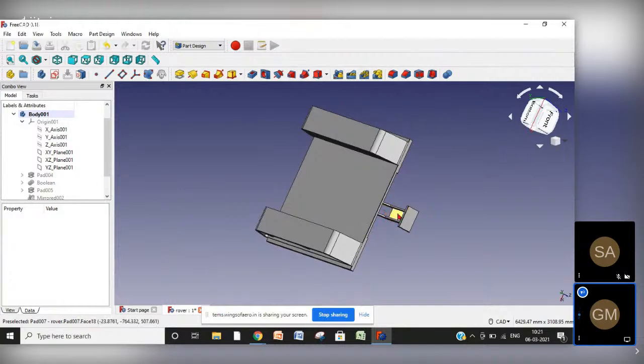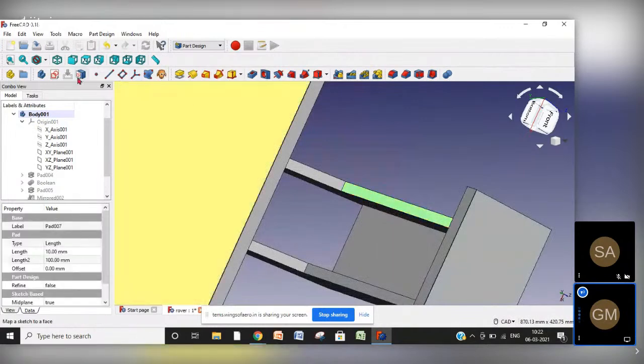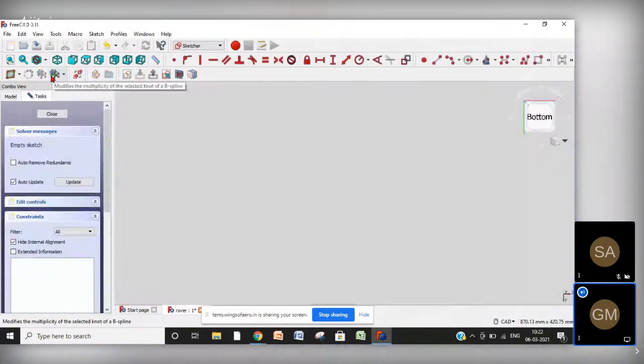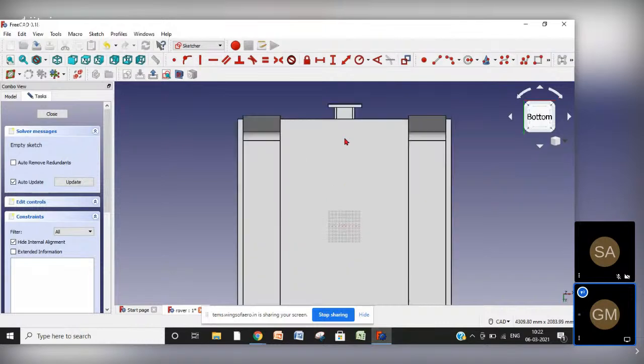If we are attaching ammunition here, an ammunition box would be there, and attaching our sensors and collecting arm, the hydraulic wires and hydraulic equipment would be in this hollow section. So what I will need, zooming in, selecting this face and sketching over it. It zoomed a lot, so zoom to fit.